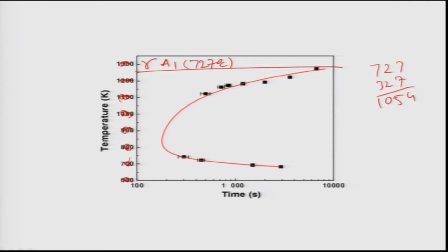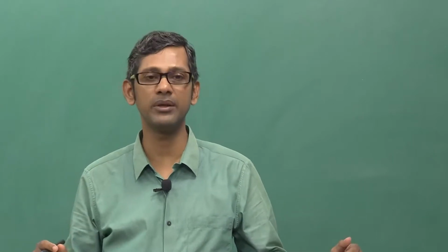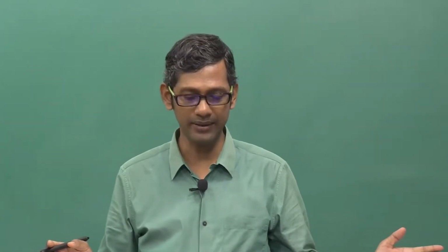So for the pearlite, when it is close to 720 Celsius temperature, undercooling is low. Therefore nucleation and growth is very slow, correct. But remember diffusion is also very fast at high temperature. So what will happen, you will have a smaller number of pearlitic lamellae present in the microstructure, but the lamellae will be thick because diffusion of carbon is high at high temperature.